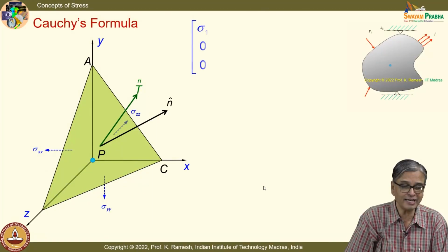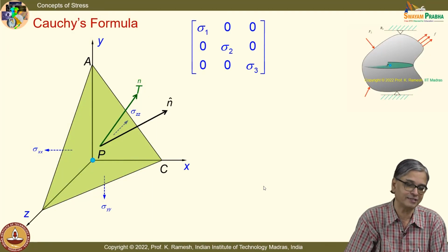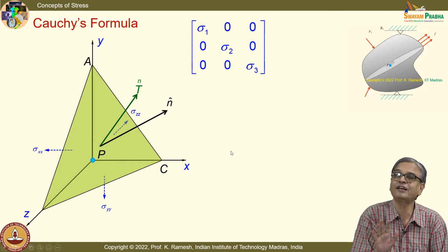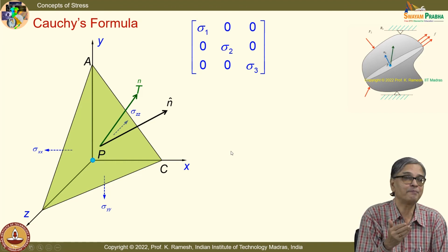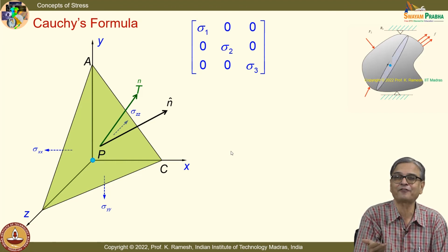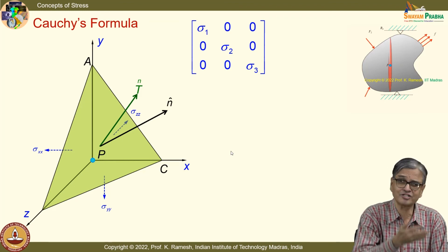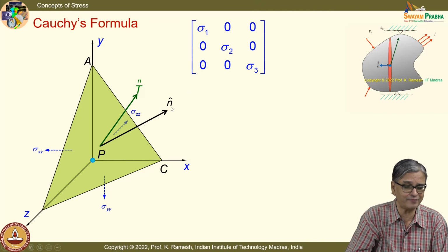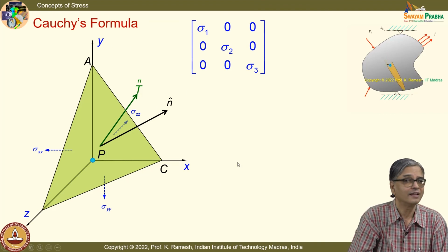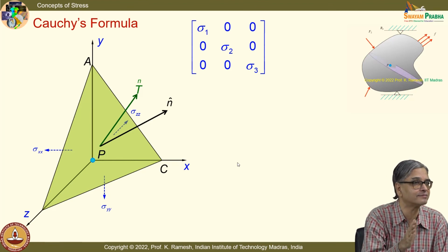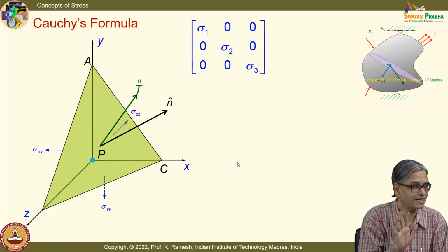Suppose I rewrite the same expression just to show that I am handling a principal stress plane. I have shown this tetrahedron in a different color, and mathematically, when you want to have a reference axis xyz, it is arbitrary. I can still put xyz in a convenient fashion and then say that they correspond to principal direction 1, 2, 3. Is the idea clear?